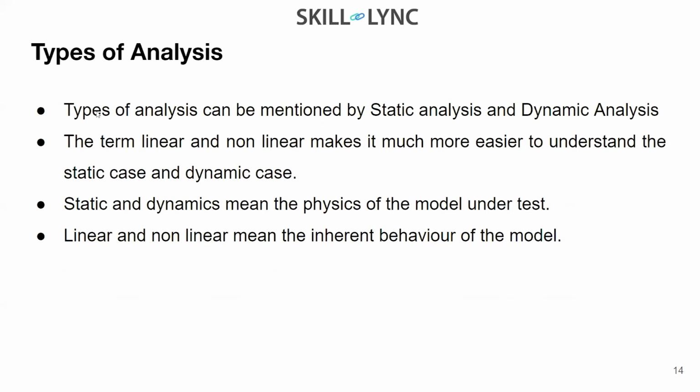Okay, the terms linear and non-linear make it easier for an analyst, a mechanical engineer or a research scientist to understand the behaviors. If I say static linear, static non-linear, dynamic linear and dynamic non-linear, what are the differences? That you should understand. That depends upon the behavior of your geometry: what type of loadings you are giving, what type of material it is made up of, what contact possibilities and joints it has, and what its degrees of freedom are. Depending upon that, it is decided.